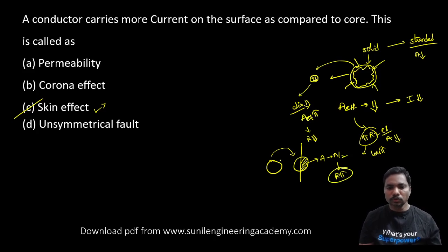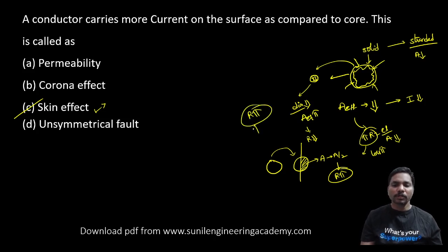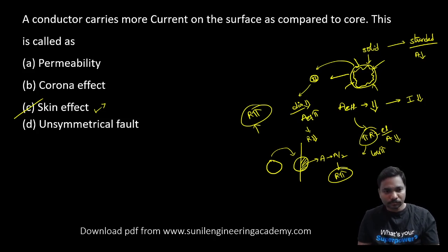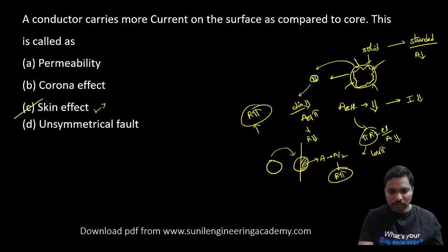So these two effects we have. Due to that, resistance will increase. A very important question: in AC, resistance is more. Why? Because of both skin effect and proximity effect. Okay, coming to the next question.